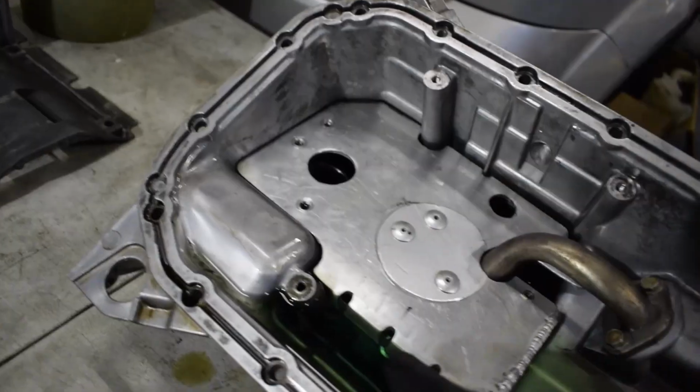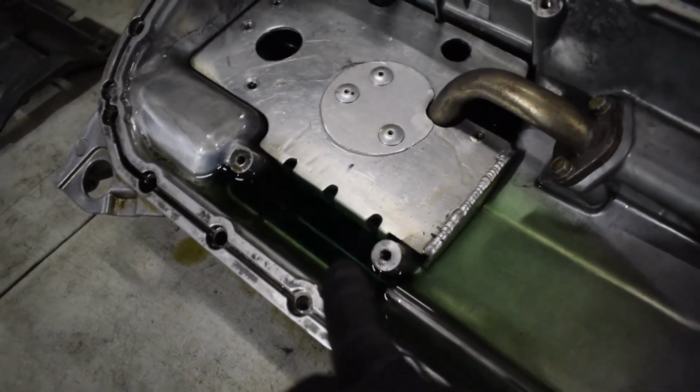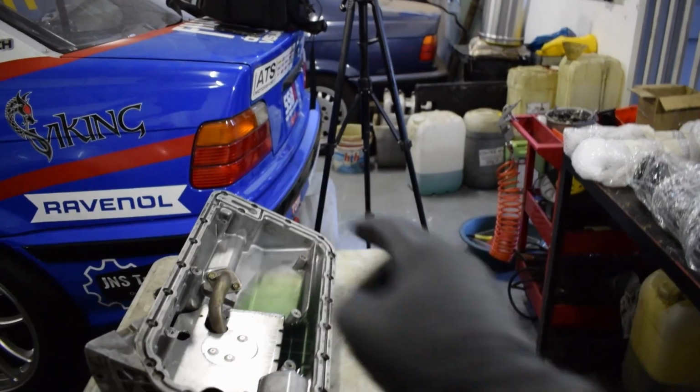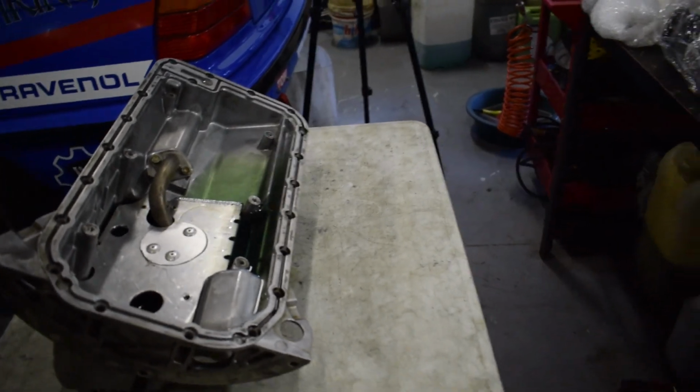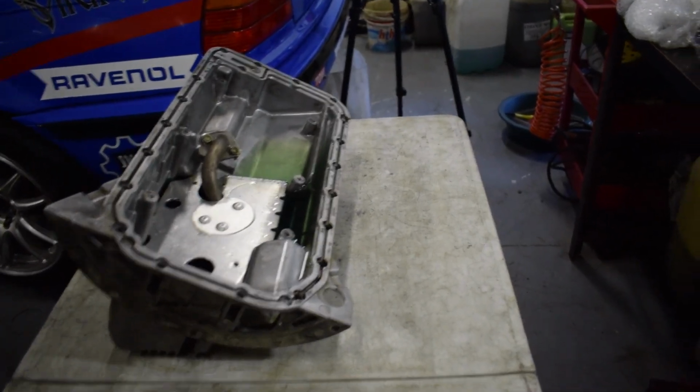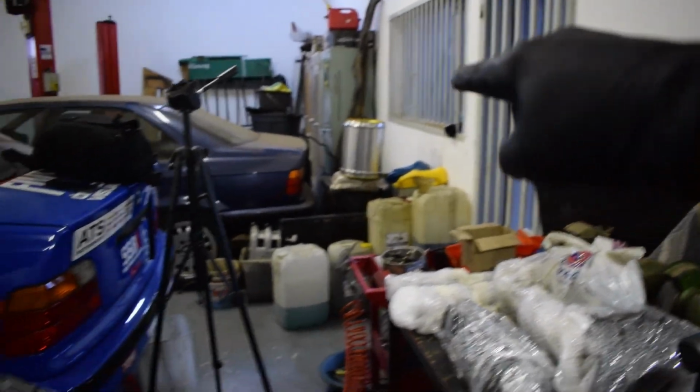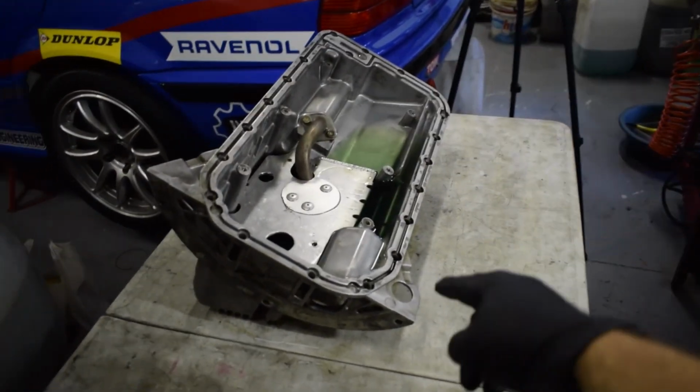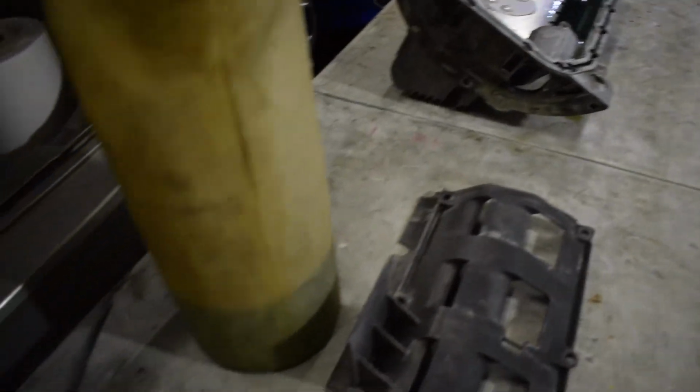So here you can see this gaping gap, and that's the front of the car, so that's the gearbox side. So through left corners it would surge right, which makes sense according to the data we've seen. Especially turn 8 at Swartkops, the last corner, it surges heavily through there, and it makes complete sense.